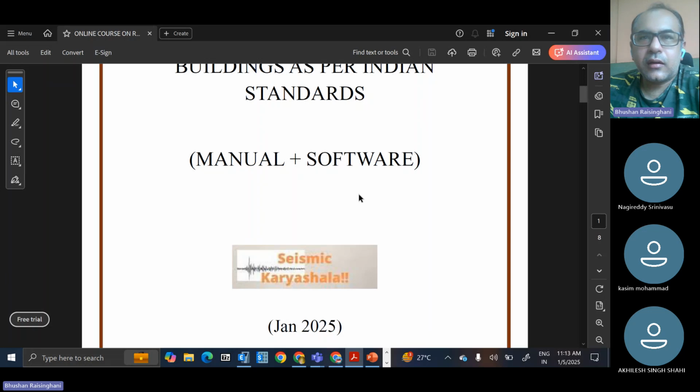But in many cases, the facade design engineers, to optimize their project cost, do the wind tunnel testing and they optimize the facade for that, not the main structure. So facade engineers use the simulation model to reduce the forces. If they find that it will lead to lesser force, they use the desktop or the wind tunnel results and design the facade for that. So we'll also go through the code that is used for facade design in these sessions.